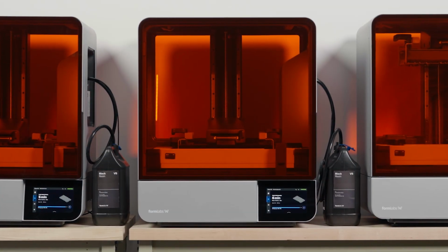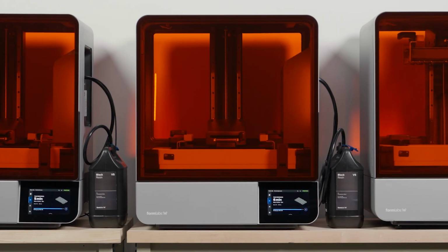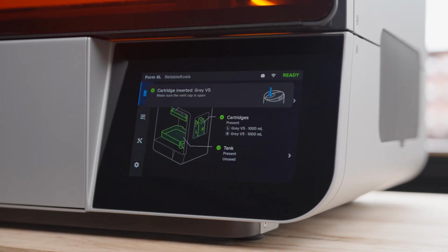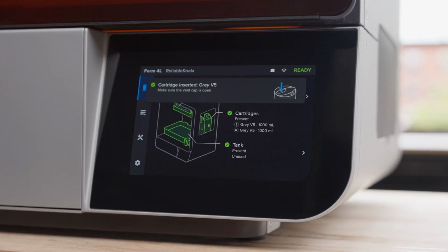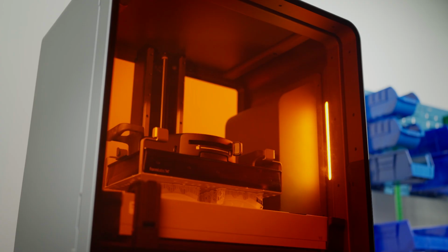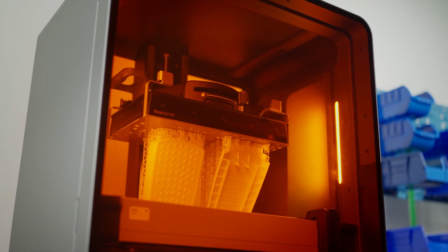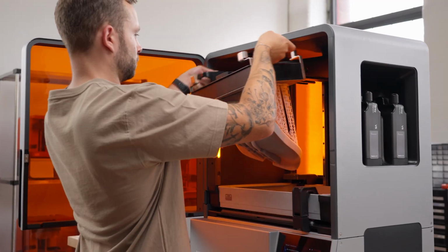An undeveloped feature is a print defect in which a chunk of your model fails to print, forming a void that widens as the print builds away from the build platform. These voids can look like a crater and frequently exhibit sharp edges and rough surfaces. In some cases, it can look like the missing material exploded outwards from the build platform.